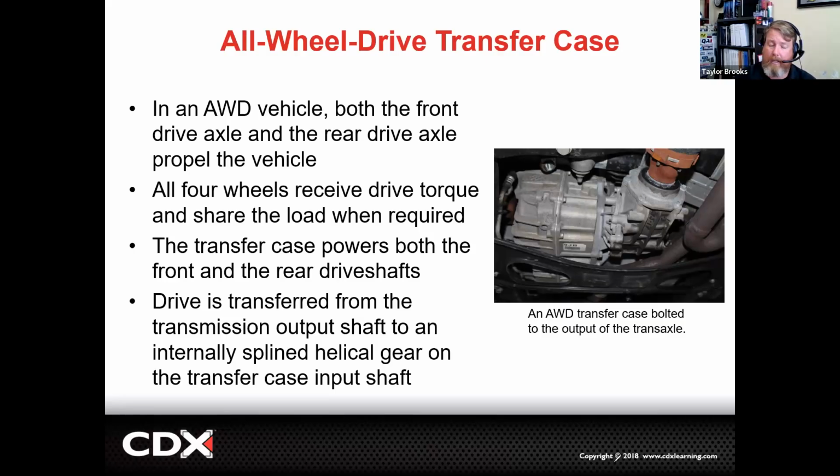And then there will be a second gearbox on the front of the engine, driven off the front of the crankshaft, that will get 10 to 15% of the engine's torque based off a computer-controlled shift strategy. That again is going to be an all-wheel drive system, not a four-wheel drive system, so it's not going to be selected by the driver.